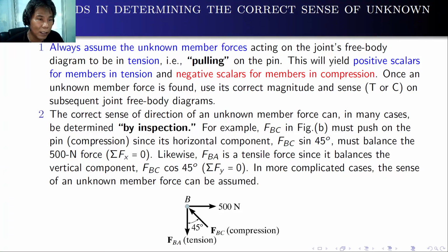So in method 2, the correct sense of direction of a member force can, in many cases, be determined by inspection. So just by using inspection, you will know if it is in tension or compression. Anyway, don't worry. You will develop that skill along the way as we go on with our discussions.